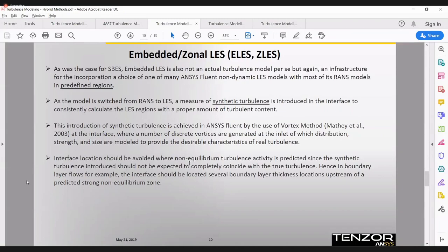So you start with some synthetic vortex generator, although you don't have to do that, you can use a tripwire, but there's a difference when you do that at an inlet and let the turbulence evolve, and when you do that when switching between zones inside the simulation. This could really cause problems.